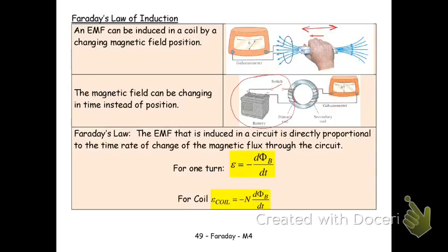But the idea is, if I simply take a coil of wire, like a solenoid, and I energize it, that's increasing the magnetic field, which is like bringing the magnet closer. And if I open the switch, that's reducing the magnetic field, which is like pulling the magnet away. So I can get this backwards, forwards effect using an electromagnet.